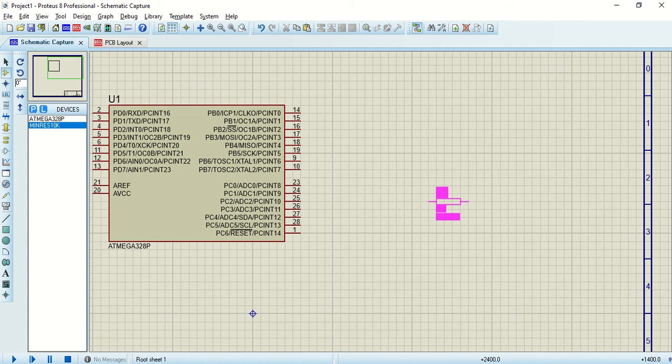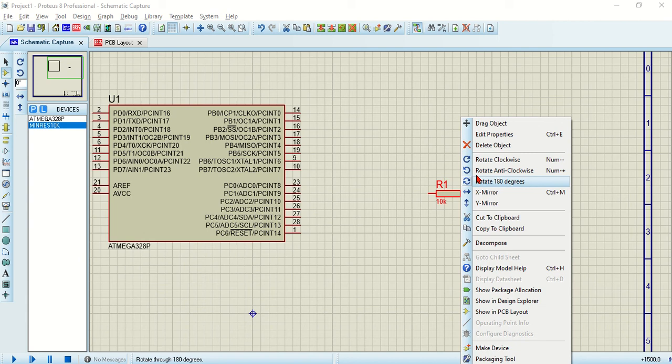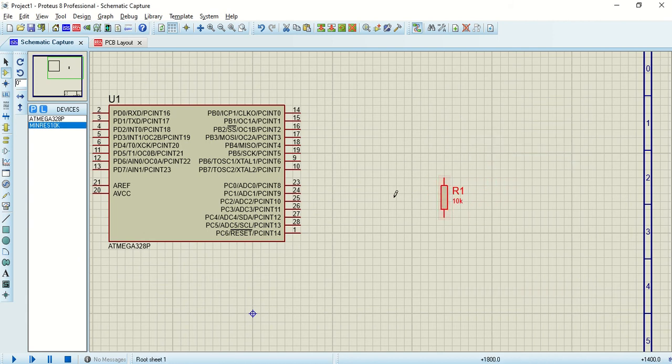So, this is placed, and click it here. So, I want to rotate that. I want to place the mouse over that, right click. There are two options, rotate clockwise and rotate anti-clockwise. Rotating. Otherwise, you can rotate here also, that is, click on here, then the two buttons, that is clockwise and anti-clockwise. Click it here, you can rotate.